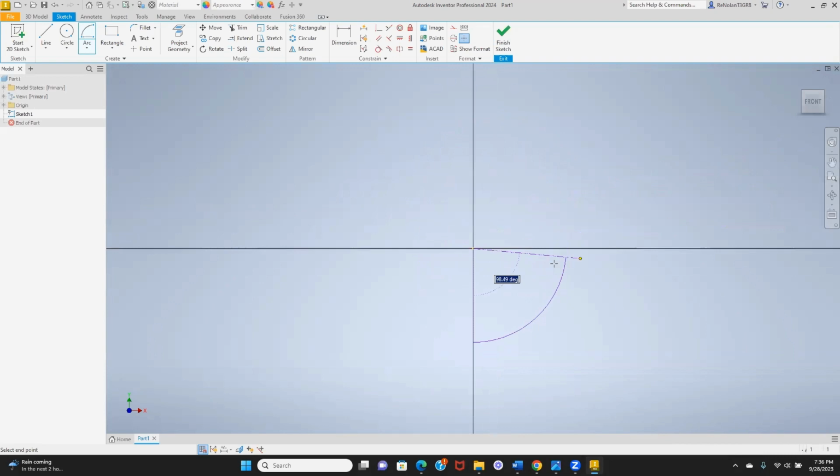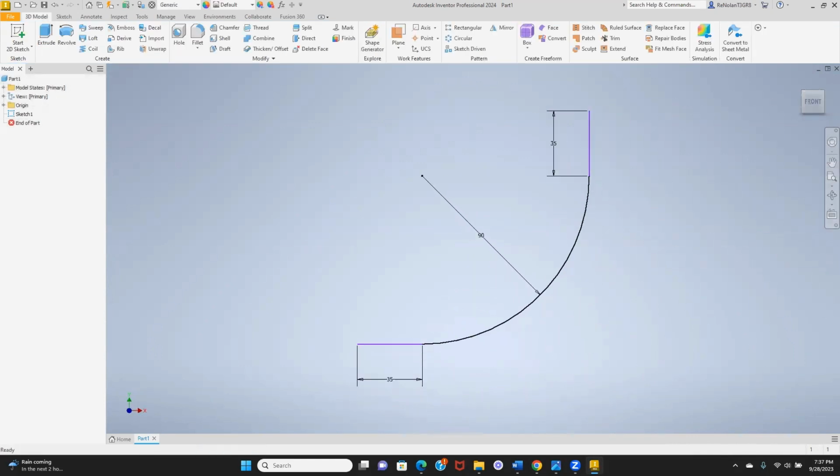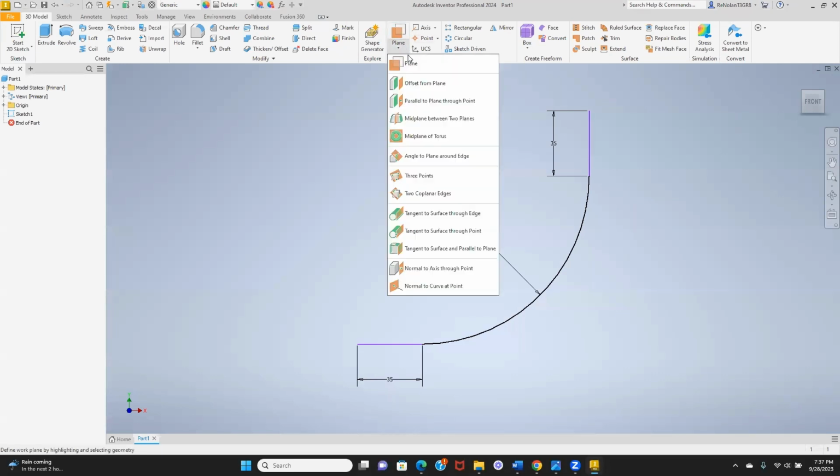Let's type in our appropriate length to get that constraint applied there. And let's set our 90 degrees. Let's add in those little additional lengths at the end. Now those are, if we pay attention to where our center lines are, there is overhang beyond that. So we want to make sure we consider that when we consider the whole path. It's going to be a sweep feature. That's what it's called. What we're going to use to get that profile, that length of the pipe.